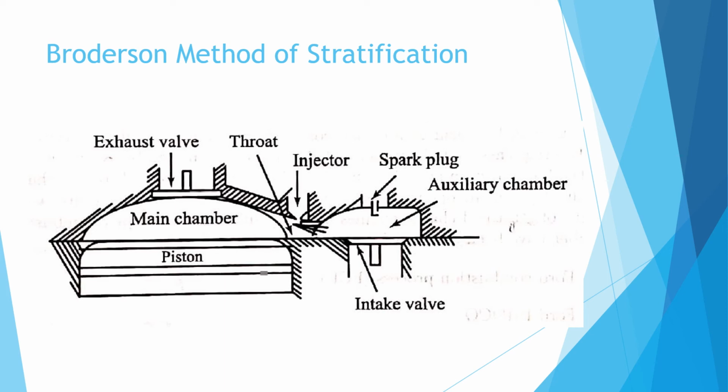One way is to use fuel injection alone, controlling the mixture strength in auxiliary and main combustion chamber by means of injection timing. Another way is to use carburation alone to obtain stratification with or without prechamber. Here this figure shows the Broderson method of charge stratification.